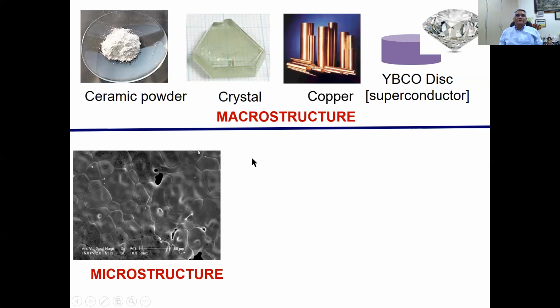So now imagine you take this block and you want to do an electrical property measurement. Let's say this is a ceramic, and you know ceramics are insulators. I want to do a capacitance measurement. So I make a parallel plate capacitor and then put this dielectric in between because it's an insulator.